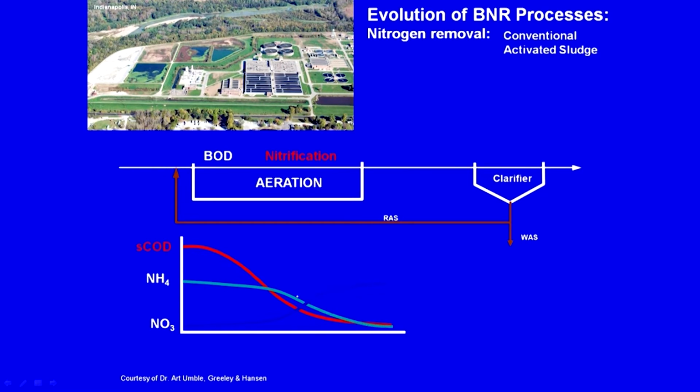If ammonia is being oxidized, pardon me, nitrates will also increase. But when will this typically take place? Only when most of the BOD has decreased, only then will ammonia start being used as an electron donor. If not, the preferred electron donor is the organic matter. Only when most of the organic matter has been degraded, well, ammonia degradation comes into the picture. That is one thing, and that is why you see an increase in the nitrate formation out here.